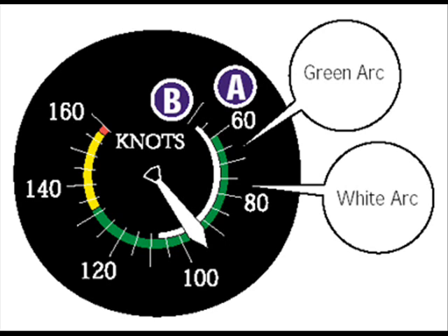This is why some aircraft manuals recommend only 10 to 25 degrees of flaps for takeoff on short fields, usually 1 or 2 notches on a 3 or 4 notch flap system. If you're too high while on approach to land, you can still select full flaps to increase the airplane's drag. It's common to use flaps only when descending within the traffic pattern and not when descending from cruise flight. After all, cruise flight descents are efficient and fast at higher speeds, where the drag is greater. If you wanted to descend with flaps from cruise flight, you'd have to slow the airplane down below maximum flap extension speed, the top of the white arc, before applying flaps. This would be cumbersome.